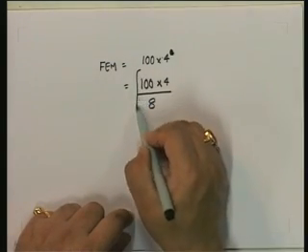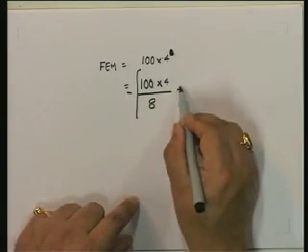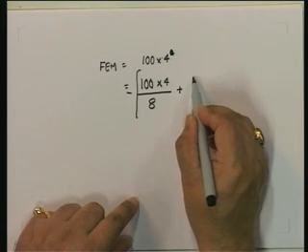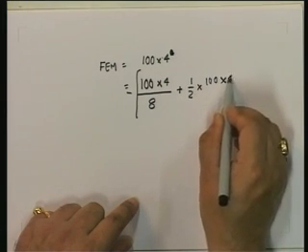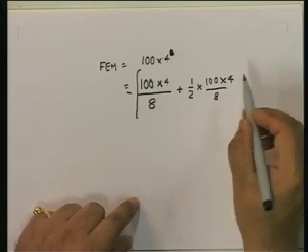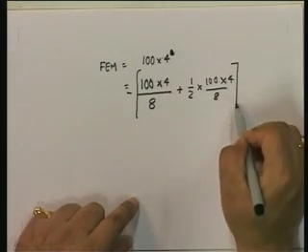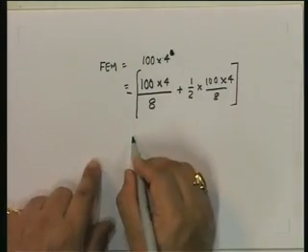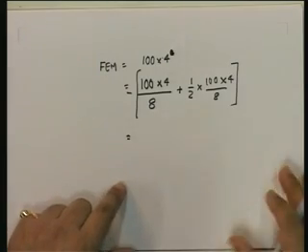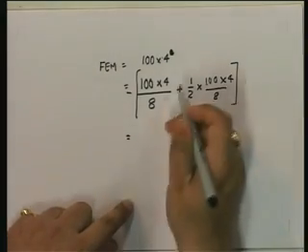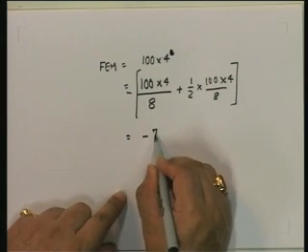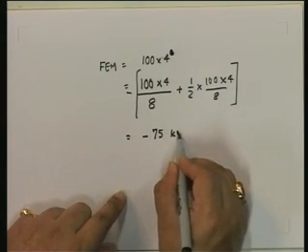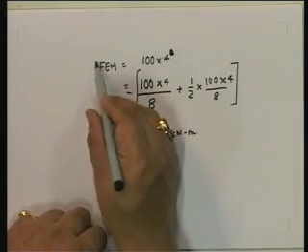So this is minus, and then plus half of PL upon 8. So please make the correction even in the previous problem, so that instead of 300, what you have over here is minus 75 kilonewton meter.